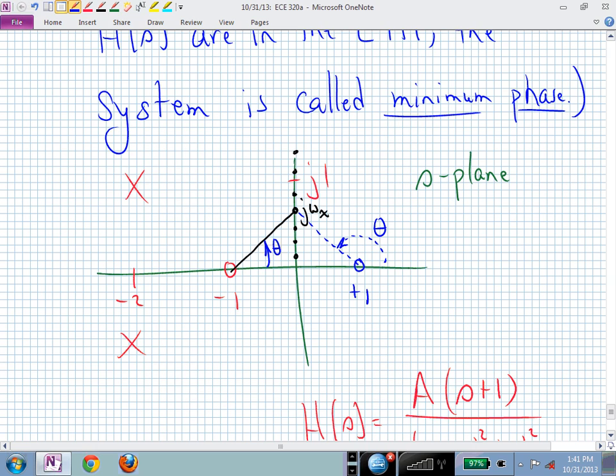I've told you how to compute angles just graphically from this S-domain picture. And that's really what we will learn how to do, maybe more systematically, by Bode plots. We'll learn how to sketch those very quickly once somebody gives us the poles and zeros of a transfer function. But now, if you needed to, by brute force, you could do that.